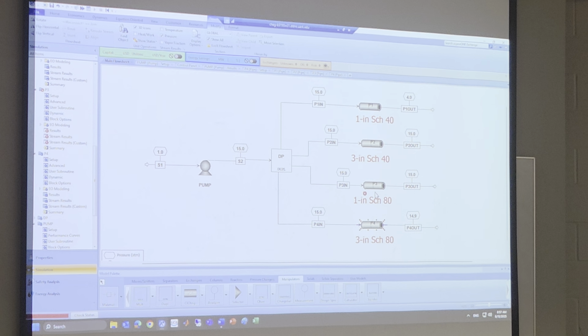So for piping 3 system, if you are design using 1-inch schedule 80 or even 100-meter length, it's not going to work. Yes, you get idea, right? But even for 100 meter, if you use a 3-inch schedule 40 or 80, you can see the pressure drop is very small, trivial amount. Maybe if you are design more than 100 meter length of piping system for water supply, then you have to use 3-inch schedule. Make sense?